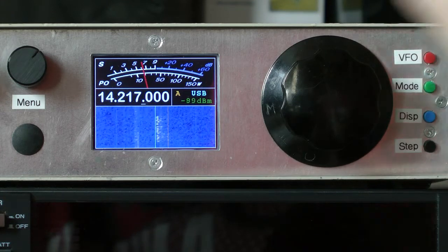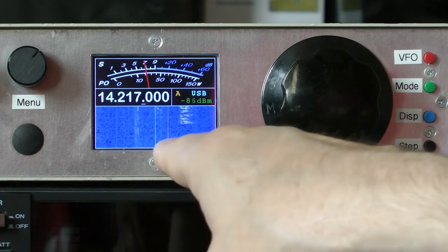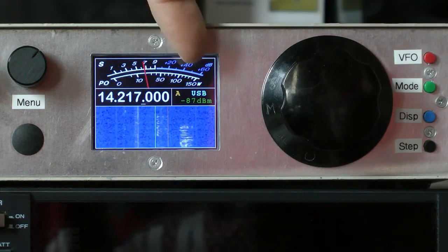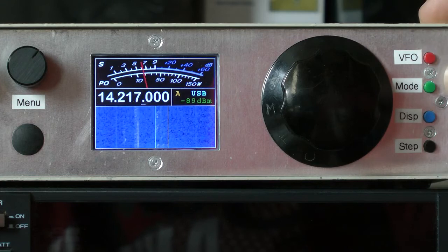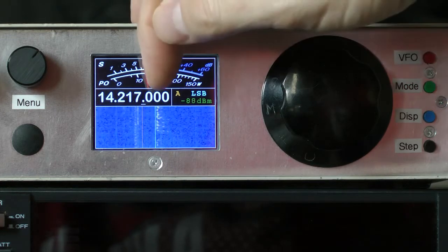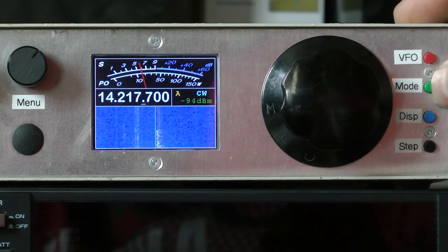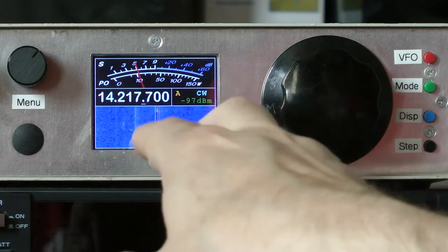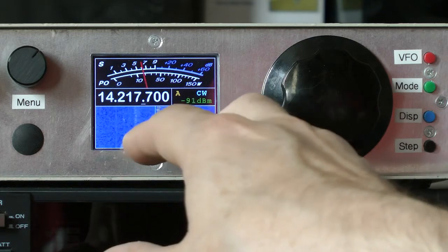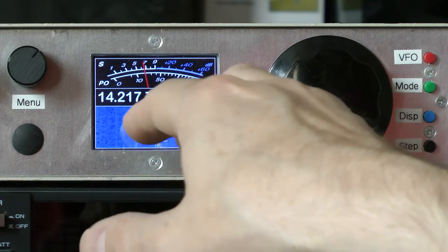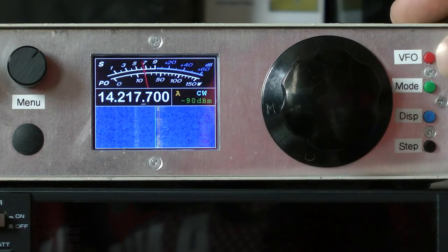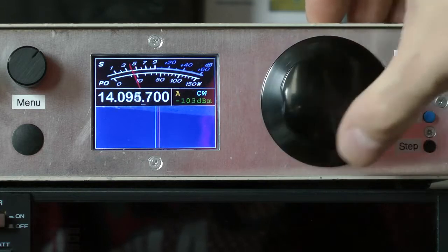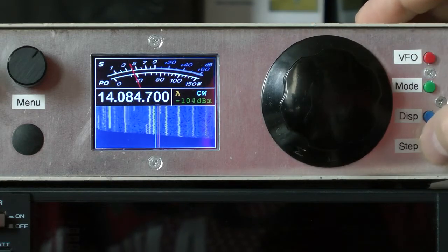If you look at the waterfall display, we can see that the extents of the DSP passband are accurately marked by a pair of purple lines. That's showing 0 to plus about 2.8 kHz for upper sideband, 0 downwards for lower sideband, and then in CW mode, centered around 700 Hz, we have the lines denoting around a 250 Hz CW filter bandwidth. So we just pop down to the CW section for a moment. Change the step size to 100.